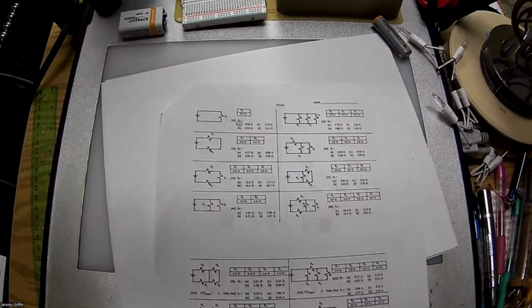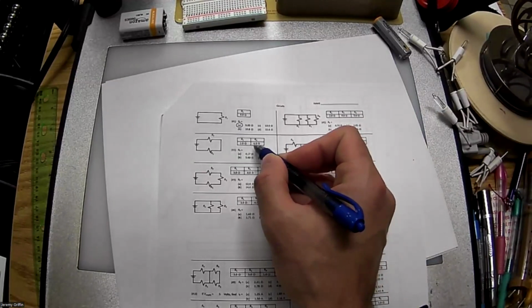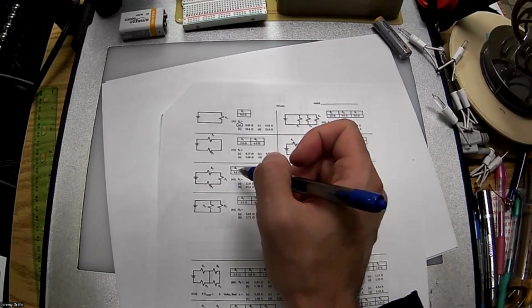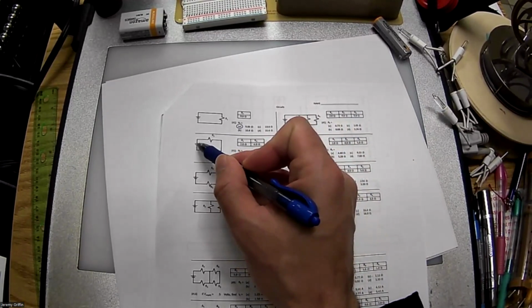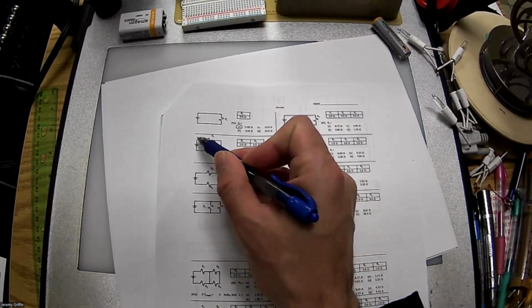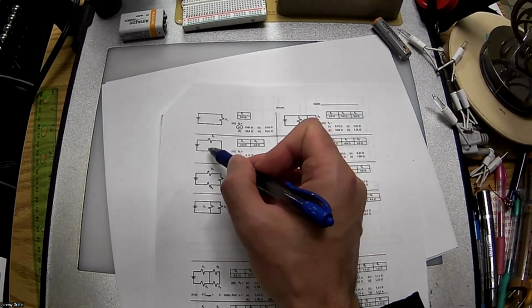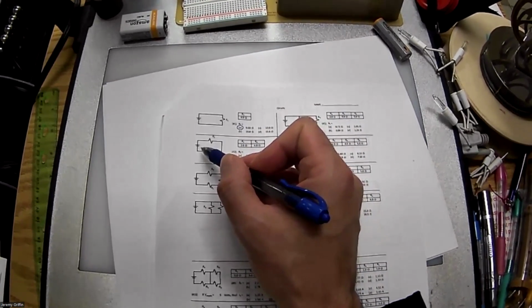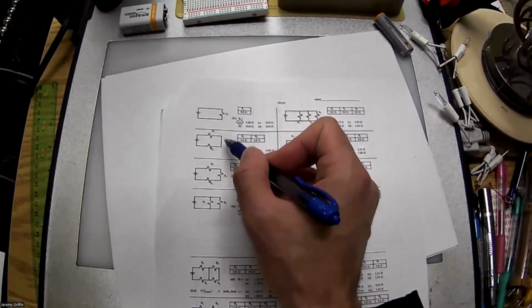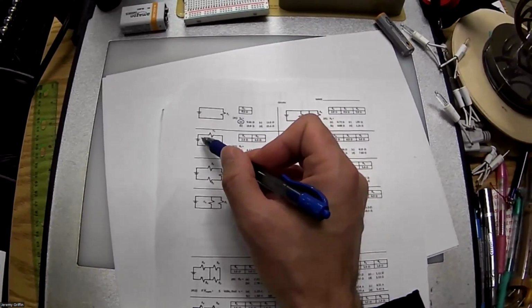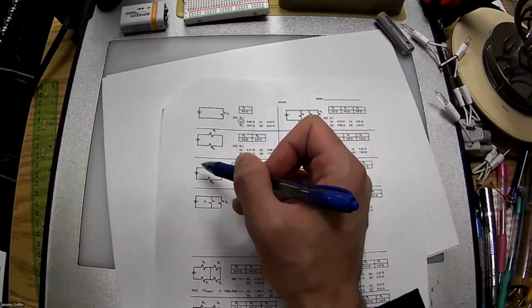Now number 2. Now there are 2 resistors. My paper says 2 ohms and 4 ohms, but it depends how they're wired up. Are they in series or parallel? Because that'll make a difference. If you start at the voltage source and trace around the circuit, you see how all the current has to go through this resistor followed by this resistor sequentially. The traffic analogy: if you start in this parking garage and drive around town, you have to go through that stoplight and also that stoplight sequentially. If there's a line of 100 cars, all the cars have to go through all the stoplights. Is that series or parallel?